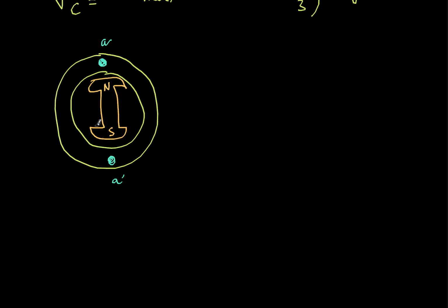Whenever the magnet poles are rotating, the flux is cut by this coil, and EMF is induced. EMF is maximum when the rate of change of flux linkages is maximum, and the induced EMF is less when the rate of change of flux linkages is minimum. That is just the general principle of working of this particular machine. Of course, in this course we are not going in depth into the machine. This is a power system course, so I'm not going into the construction of the machine.